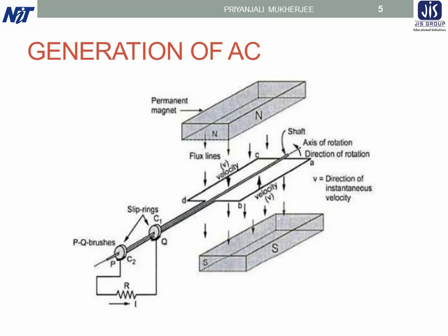Now consider a rectangular coil with n number of turns rotating in the counterclockwise direction with angular velocity omega radian per second in a uniform magnetic field. The time is measured from the instant of coincidence of the plane of the coil with the x-axis, and at this instant the maximum flux phi max links the coil.